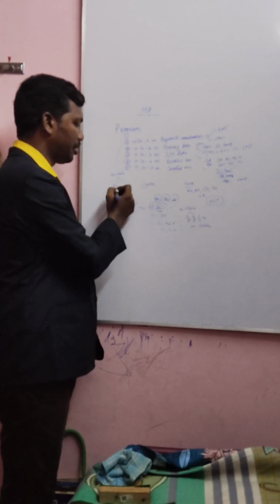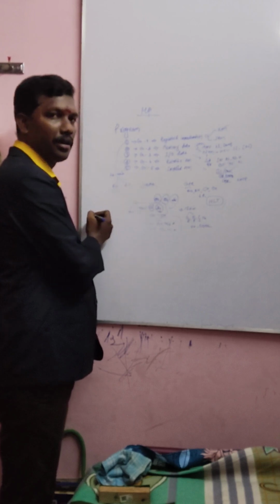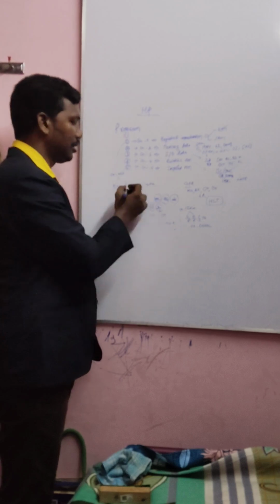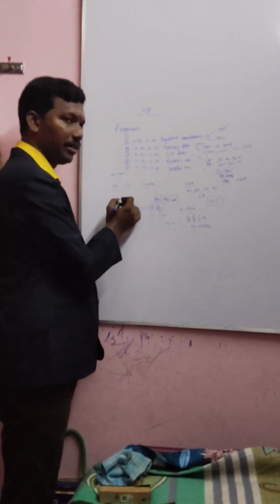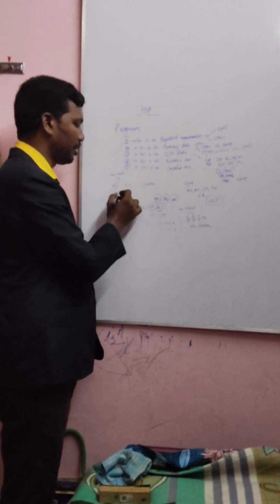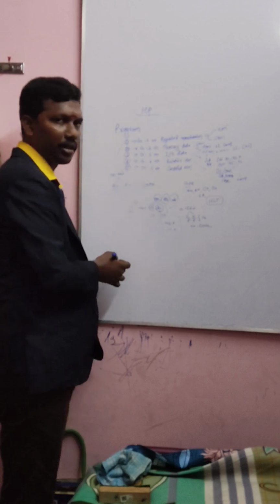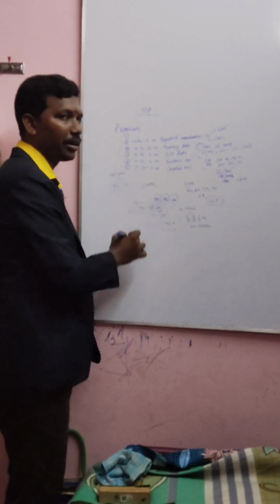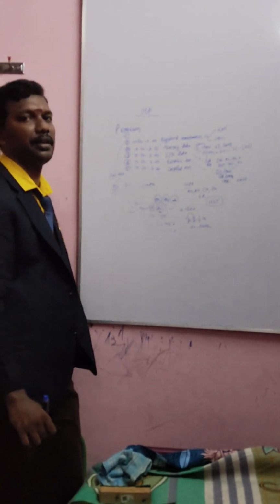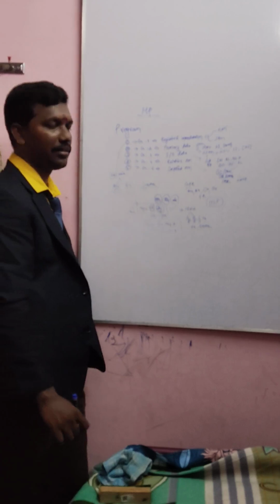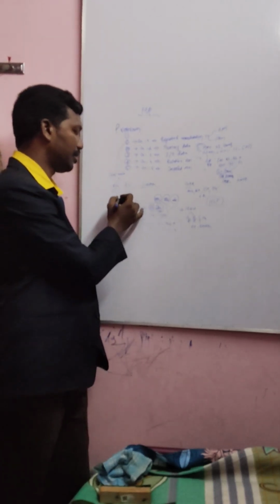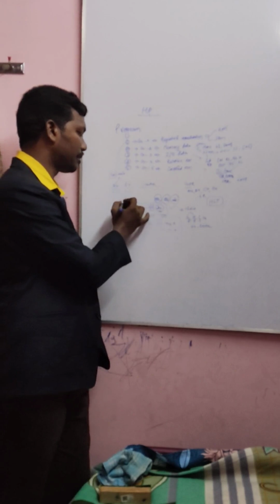The bus interface unit does communication between each and every category present in the architecture, and the execution unit does the decoding and executing, while fetching is done by the bus interface unit. As I already told you, the processor is a program-controlled semiconductor. It's an IC. The function is fetching an instruction, decoding the instruction, and executing. This process is called pipeline architecture.